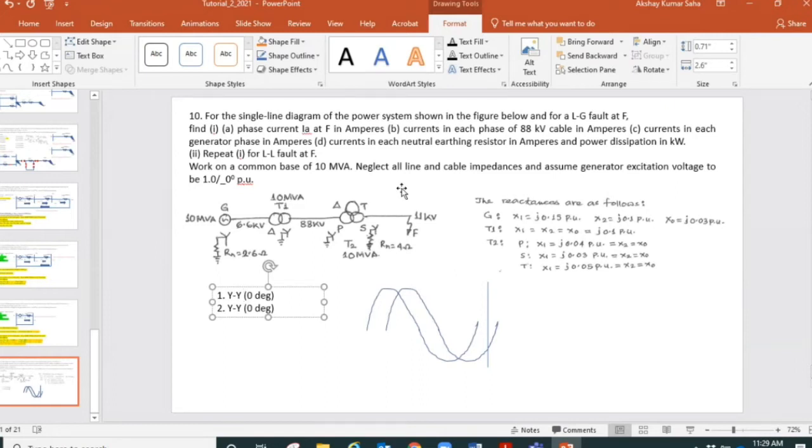So when we have transformers in the upstream, we have already shifted the voltage by 30 degrees plus or minus. And now I want to connect another one, but I cannot shift anymore, because if I shift, then the voltages will be shifted, and then I won't be able to connect them in parallel. So I don't need any shift. So I will go for star-star 0 degree. With star-star, it's also possible to shift by 180 degrees. It's not only 0 degree.